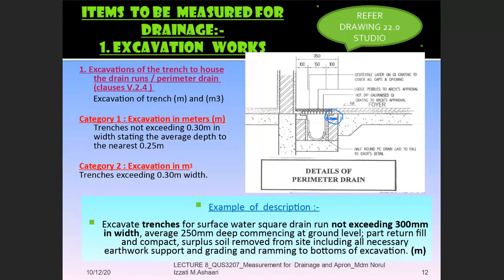Okay, right. And then for the plastering, this is actually plastering. If you zoom properly, this one we have two plastering. One on the surfaces of the lintel, another one on the surfaces of your brick wall. So these two have to be measured separately. Okay, class? Any question on the drainage?